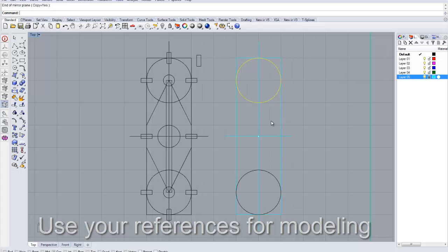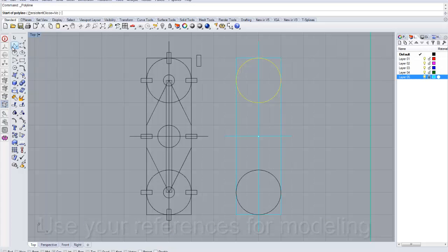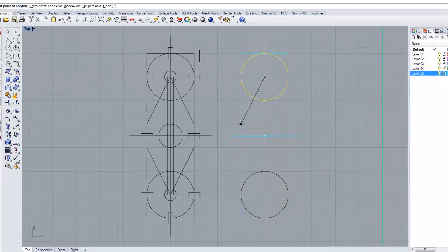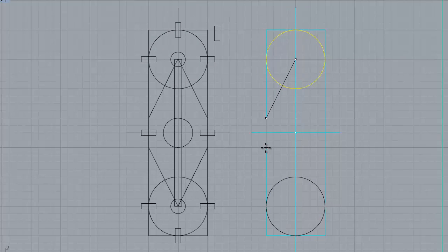And now I'm going to draw with my line here. I'm going to draw a line from the center here. Let me turn off my center snap and my ortho snap. And I'm going to draw a line there, 2 units, 1/2 inch, there, that way, that way, that way, and that way, like so.